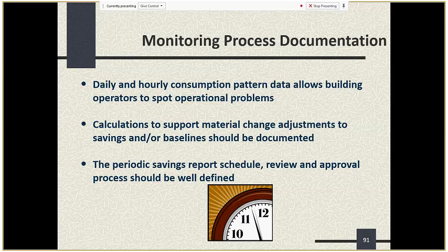You might also need that monitoring data to calculate a baseline adjustment. A good example there is the ventilation fans. In order for JCI to calculate their savings adjustment for that particular ECM, they needed monitoring data from the EMS system to see what the target speed was, what speed they actually ran, what speed they were designed for, and figure out what was going on.